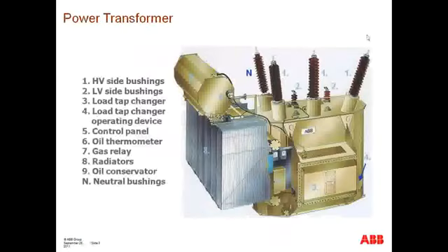This is now a picture of a power transformer, and there are some elements worth mentioning. First and foremost, we have these big towers, which are your big insulators or your high voltage bushings. In this particular case, these are bushings that provide proper insulation from this point onto the tank of the transformer, which sits at ground potential.